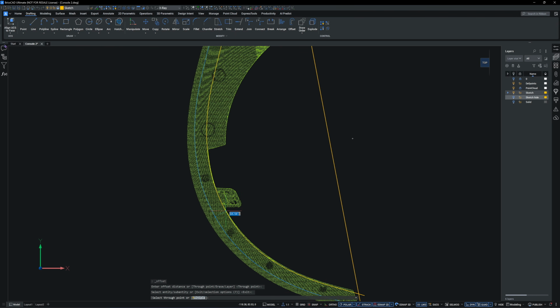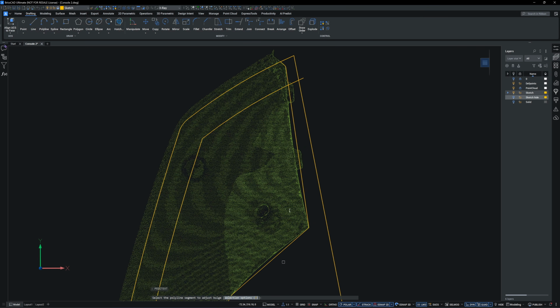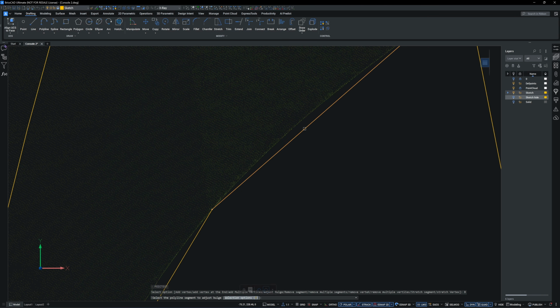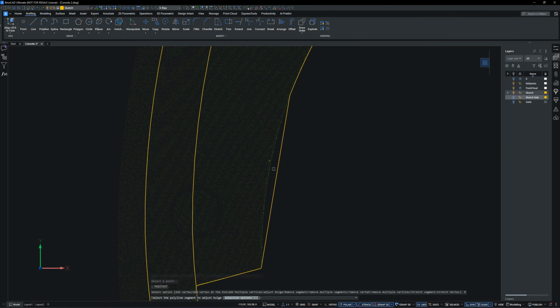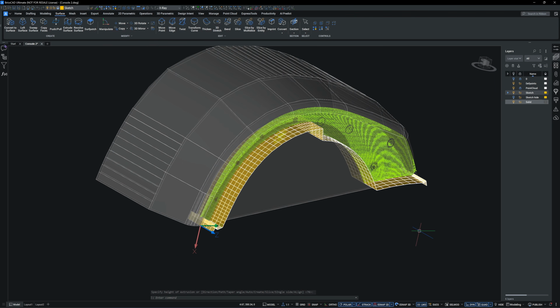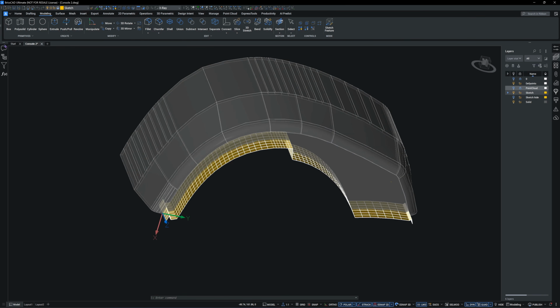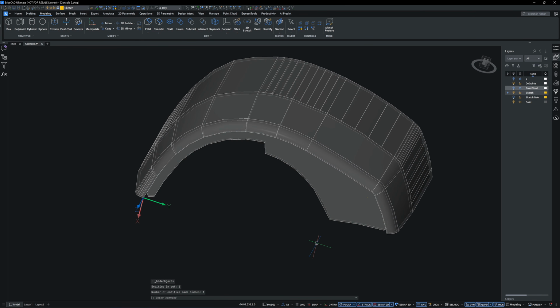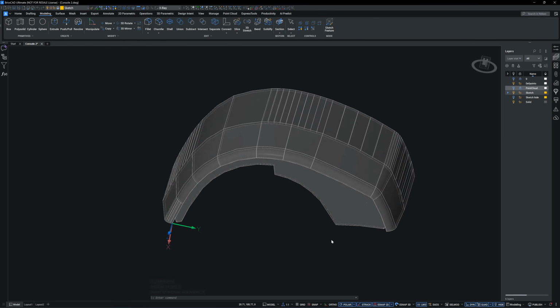Next, I will create the sketch to cut out the side wall. I will crop a thin slice of the point cloud in this area, trace the lines, and form closed loop sketches. For a quicker method, you can simply extrude polylines into a surface and use that surface to slice the solid. This approach is faster when trimming complex geometry.